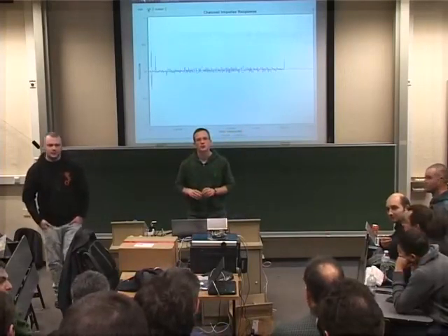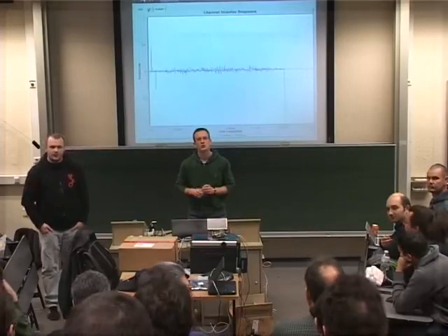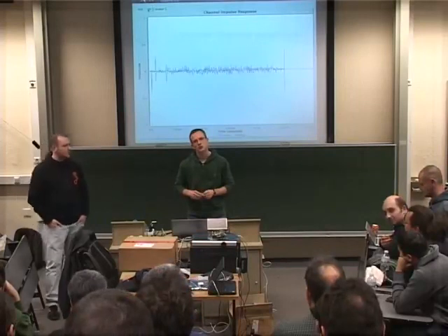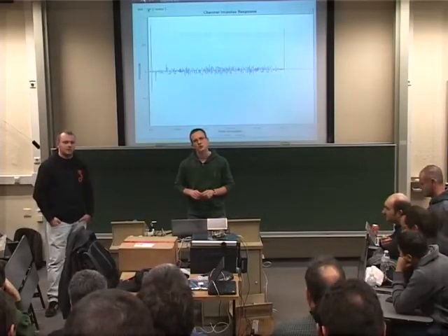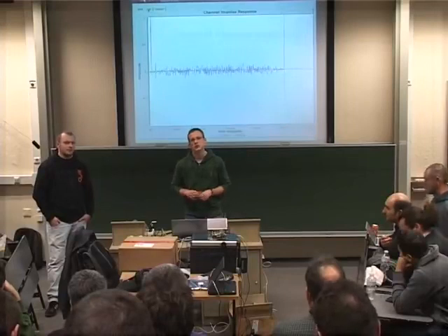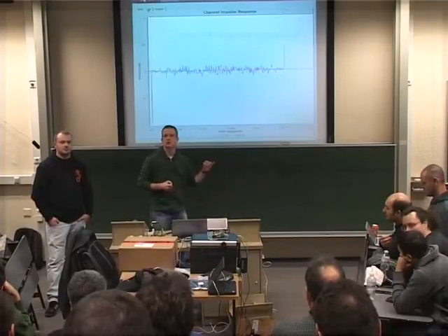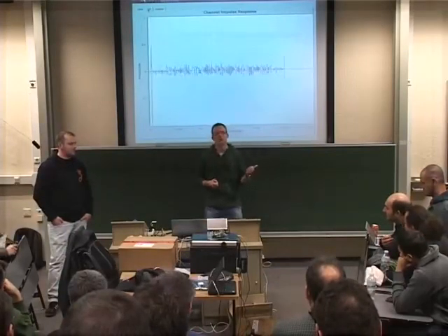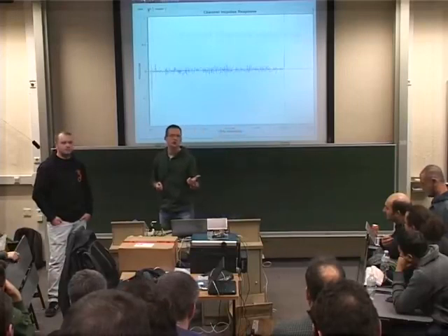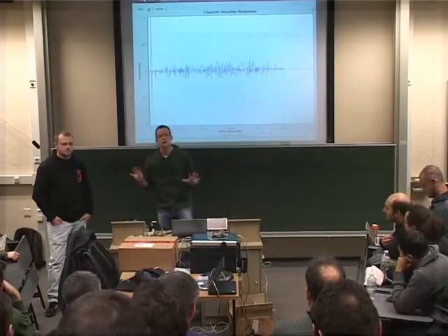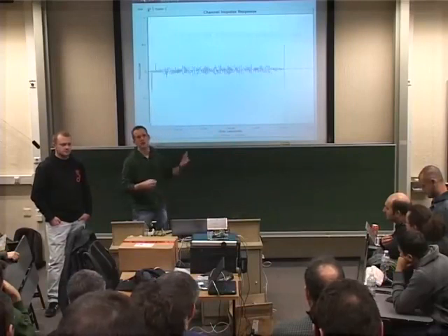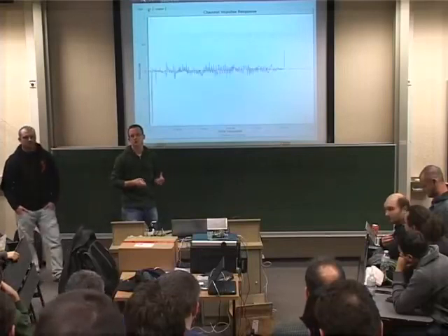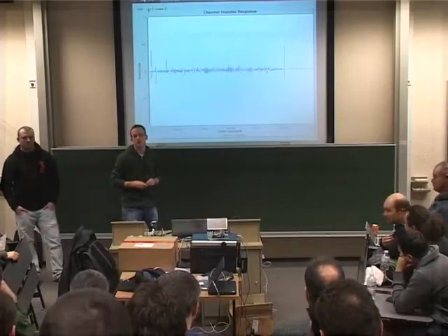Sorry. For the COST 207 model, do you choose an environment, to say it's GSM, mobile, or countryside? So you're asking about the COST 207 channel models. Basically there are 4 propagation environments. I think there's one for typical urban, then bad urban, hilly terrain, and rural area. So you have those 4 channel models, and then depending on what kind of simulation you want to run, you can plug in one of these. So you select inside, I want urban? Yeah, exactly.